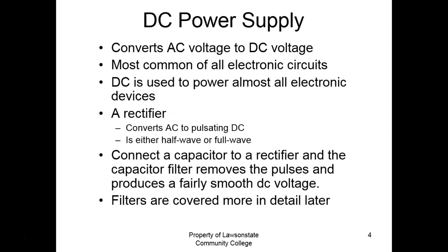So what we're talking about is, a battery is unregulated. That means if you put a load across the battery, it's got nothing to compensate for the internal resistance of the battery. So right off the bat, as soon as you put a load across the battery, the voltage would drop down some, because there's no such thing that has no resistance, right? You understand that? So a battery has internal resistance, and if you put current through resistance, then you're going to have a voltage drop. And that's why batteries get hot when you try to get a lot of current out of them, right? You understand? Because you're putting current through resistance.